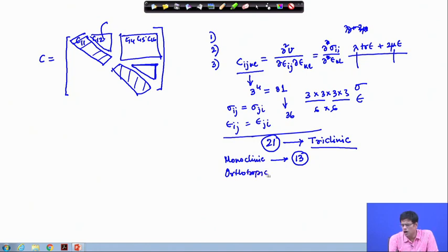where instead of one plane of symmetry, we assume another plane of symmetry. Since if two planes are mutually orthogonal, the third plane will essentially also have the symmetry. So, finally, the orthotropic material has 3 planes of reflection symmetry. That further reduces the number of material constants to 9.